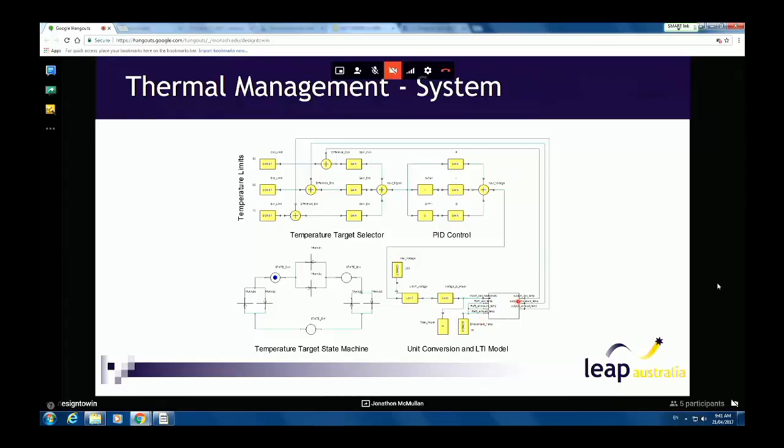And then this model calculates in real time what the temperature of the coil is, what the temperature of the enclosure is, and how hot the exhaust temperature is. So these numbers are fed around this loop here, and we end up back in the selection stage. So we can set different targets depending on the particular temperature we're measuring. So for example, the coil temperature limit is 90 degrees Celsius, because at that stage the plastic starts to become malleable and we start to damage the device.